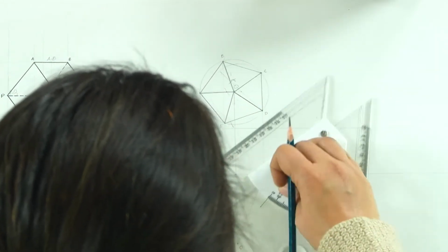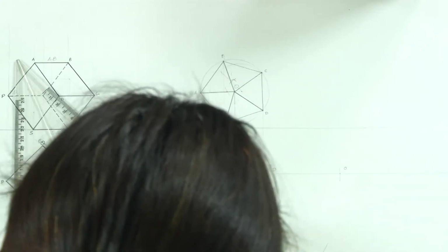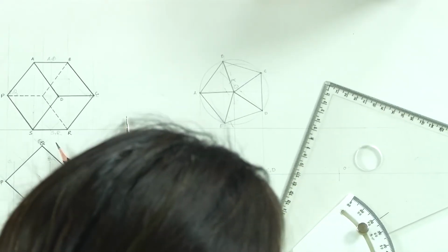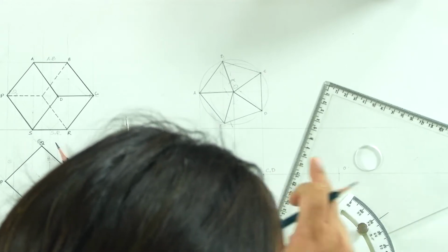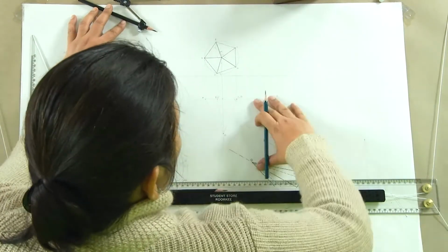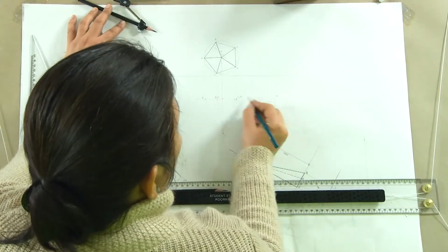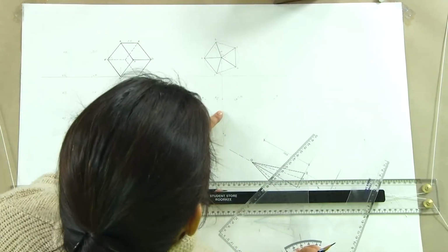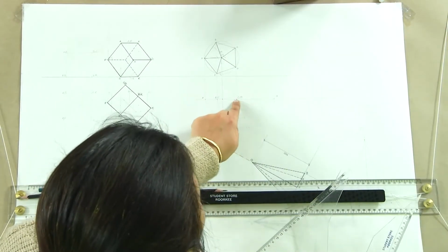So if I set my set square about the parallel, which is here, by a certain degrees, this is the angle which this line is making with the horizontal. So when we incline this in such a manner that OC and OD both have become parallel to VP, we will rotate this entire thing about this line CD.